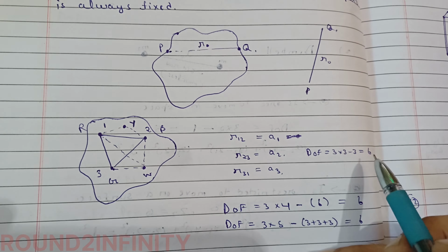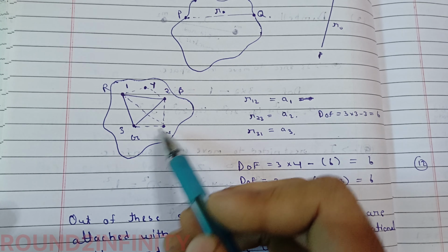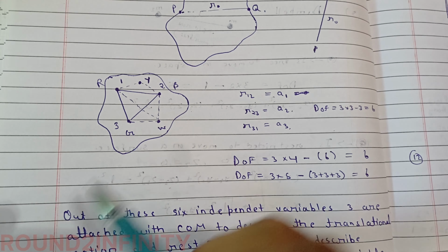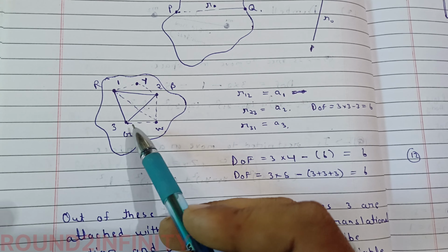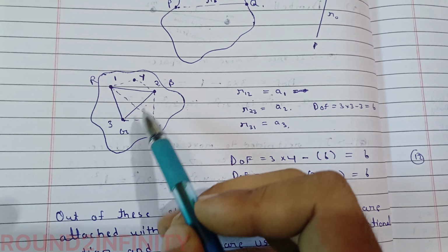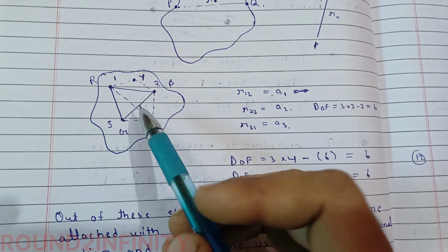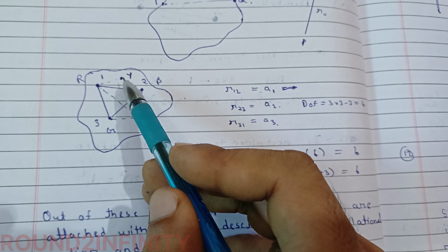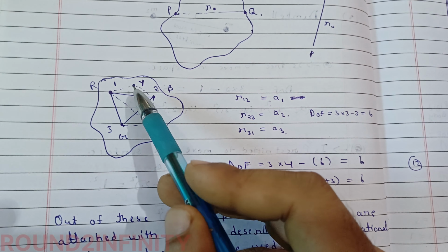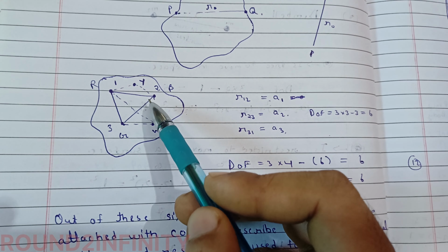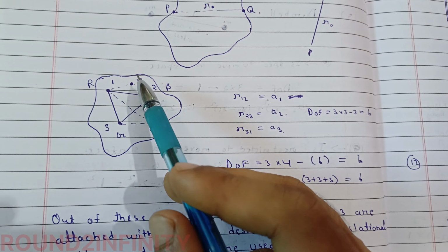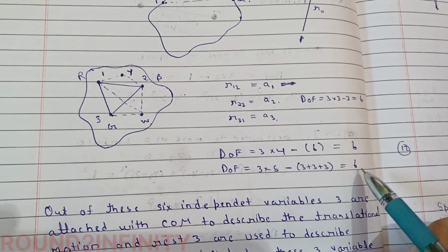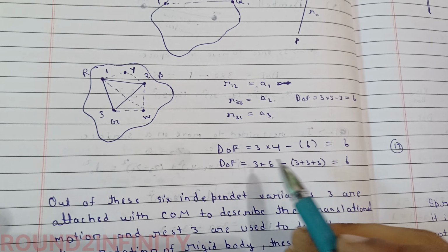Now this is the interesting thing: what if you have one more particle, then for this 4 particle system, what is the number of degrees of freedom? It will be 3 times 4, 12, minus, now see, 3 are already involved, and with this coming in it will be 3 more constraints, so 12 minus 6 will give you 6 again. Now let's say one more particle is there, so it will also give you 3 more constraints, so 6 is already there and 3 with this, 9, so you will get 6 again. So what you are seeing here is that the degrees of freedom always remain 6.